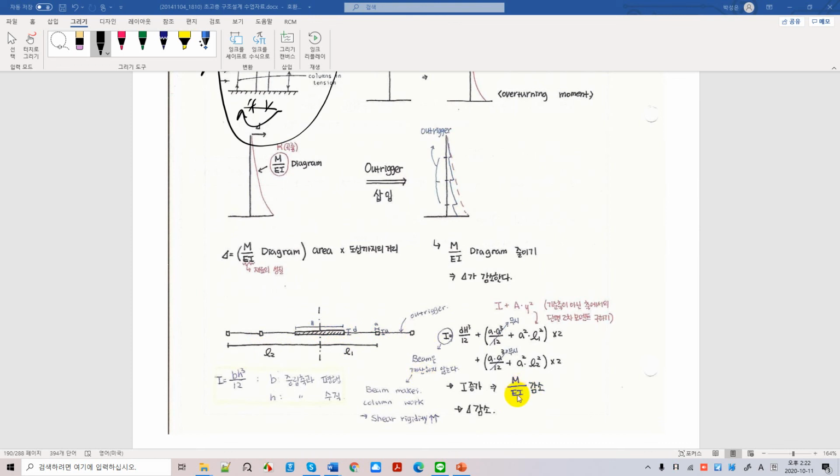When you increase your I in the denominator, it will decrease the entire value here, so that your loading decreases, and a loading discontinuity is found at the level where you have an outrigger, of course, right?